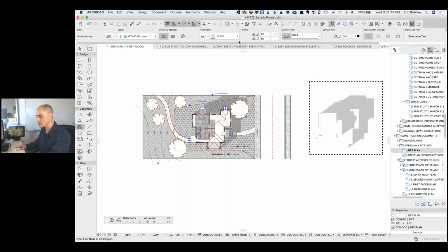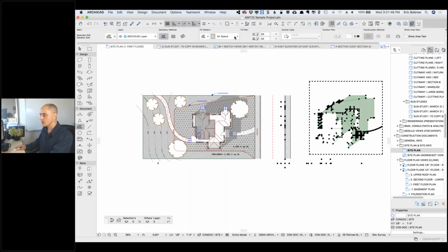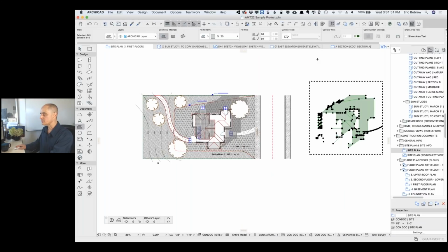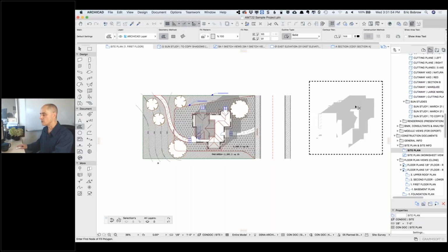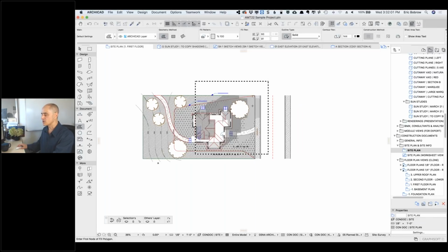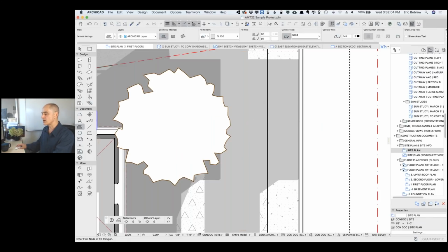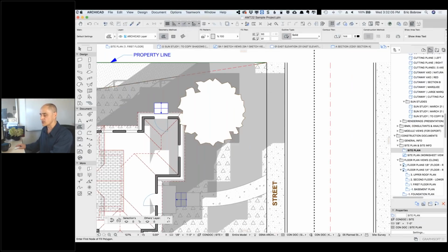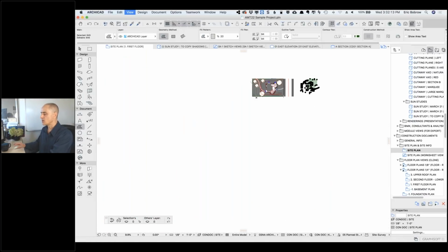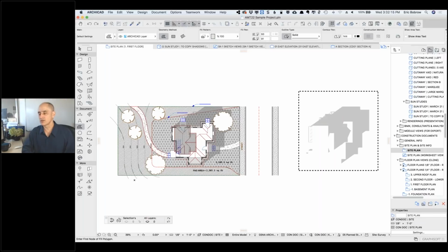Or I can say select all those ones and make them 20% here. So now this would be, if I were to drag these over, I'm just going to drag them over, not the right distance, say 90 feet, and you'll see that they've just come in on top of the other elements, but a little bit offset because I didn't do the 100 feet. But that's how you can, and I just undid it, so now it's back to where I had it. So that's how you can get shadows.